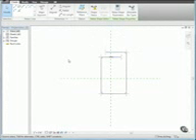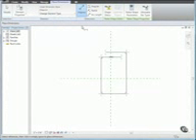and let's place dimensions. We'll add dimensions which define the length, height, and width of the rebar to the new shape. These dimensions are used to control the parametric relationship of each element. From the Dimension panel, click Aligned. Then, making sure that you snap to the reference planes, place dimensions on the sketch as shown.